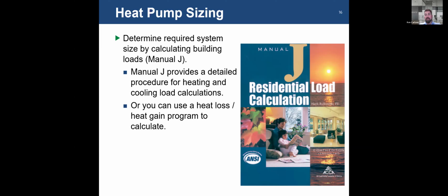In my past, 40 BTUs per square foot gets you the heating that you need for the dwelling. It gets you probably close, but that's a very old number based on contractors from 60 years ago when it was 2x4 construction, loose housing, poor insulation. That rule of thumb doesn't apply anymore, particularly if you're in a newer home that's not 65 years old. So you can really end up oversizing equipment by using those old rules of thumb, or just replacing exactly what's there, particularly if that unit was installed 40 years ago.